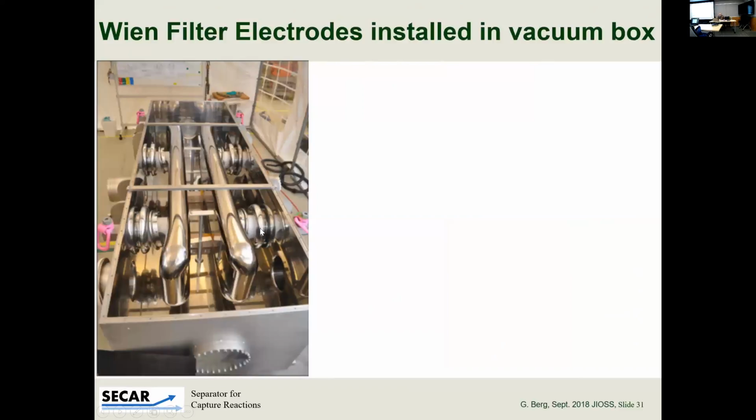You see here these little rings. There's an issue with what is called the triple bond. Where you have a vacuum, ceramic, and metal joining, the field can be humongous if you don't address it. So at this point, you need to shield from as much field as you can, and they're shielded by these so-called corona rings. So there's a lot of high voltage engineering going into this. I'm not going into that here, just so that you know.